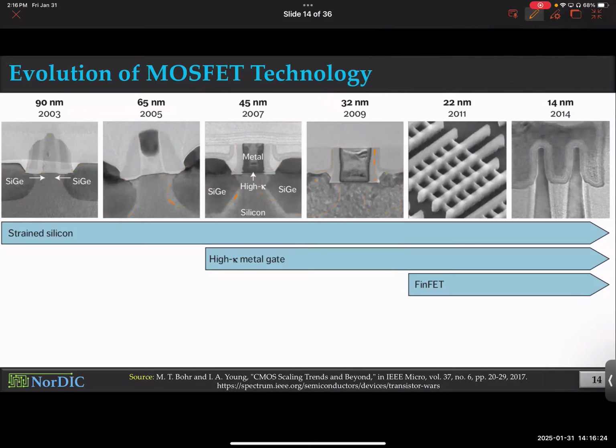So for the most modern circuits, since you will be dealing with the most modern memories, you will be dealing with FinFETs mostly, okay? And don't worry, when we simulate in class using HSpice, we'll be using both MOSFET and FinFET, and I'll show you how similar they are and how easily you can ignore the underlying difference if you want to. If I ask you to draw the ID-VGS characteristics of FinFET, they will look exactly the same as MOSFET, okay? So you don't care if you don't want to.